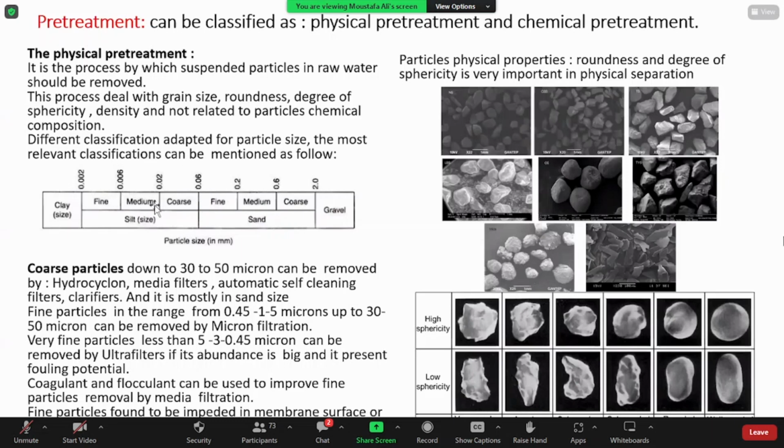And for the particles less than sand size, we call it silt size. It ranges between 64 micron down to 2 micron. Less than 2 microns, it is a clay size, as we say. So this nomenclature is just used as grain size ranges, not as a composition, to represent grain size range, not composition or mineralogic constituents, or chemical